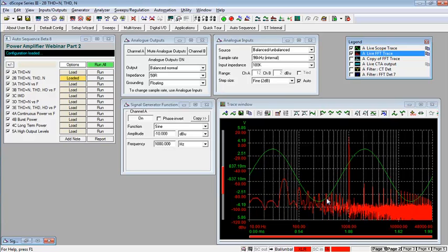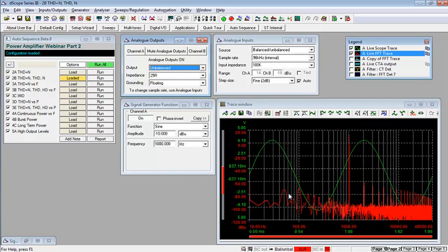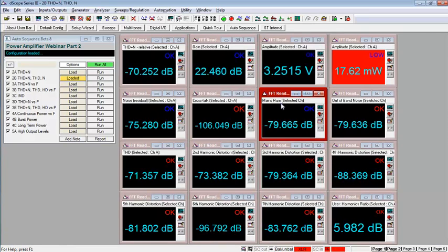I can actually reveal that the reason for this particular failure, the reason why my mains hum is reading high in this case, is because I have inadvertently misconfigured my test system here. I've got an audio amplifier with unbalanced inputs, but I have set the test system up with balanced outputs. So there's no reference to ground at the signal generator output. Now if I switch to unbalanced, the 50 Hz signal drops significantly. And if I go back to my noise and mains hum readings, these are now looking okay. So I've solved that problem, but there still seems to be a problem here.